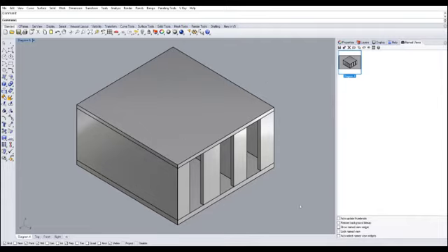So now that we have our views nicely saved, it's ready to go. Next step is, of course, to set up our view array. So let me close this first. If your view array option, the tab that I just closed, isn't available or seen in front of you, then simply turn it on. To turn that on, all you have to do is go to the render option of the file menu, go to Current Renderer, and then make sure V-Ray for Rhino is clicked on.